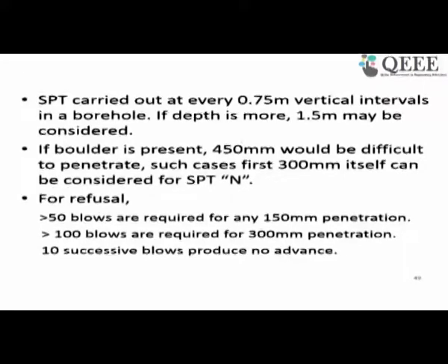If they are varying a lot, and every 1.5 meters or 1 meter the strata is changing, then you need to do an SPT test whenever there is a change in the profile. If boulders are present, of course, the penetration will be very slow or you may not get any penetration. So 450 millimeter would be difficult to penetrate. In such cases, the first 300 millimeter itself can be considered.